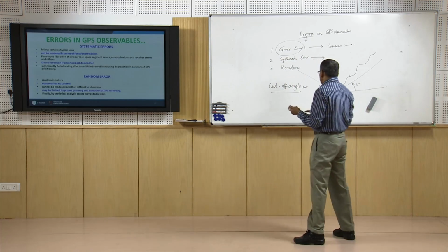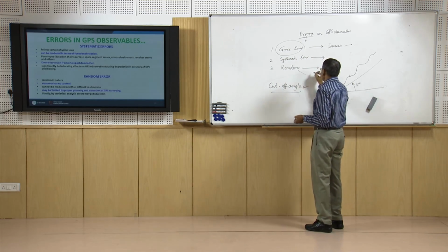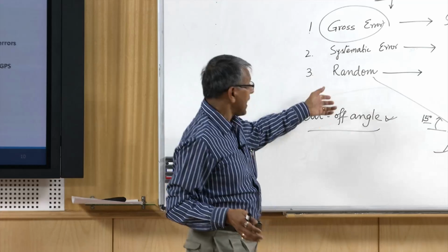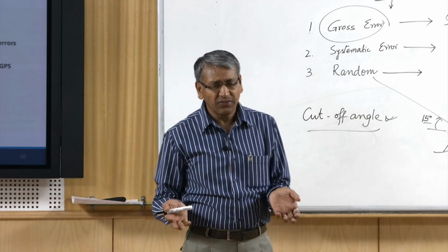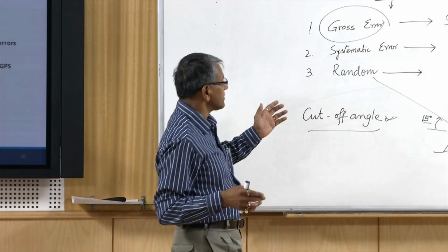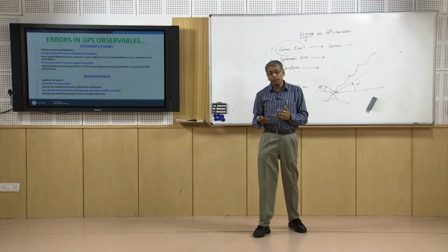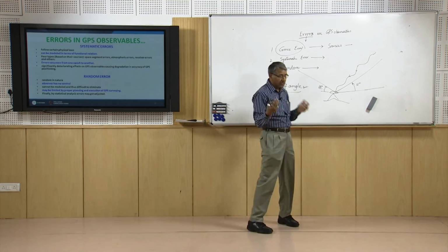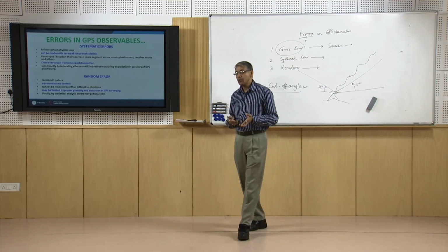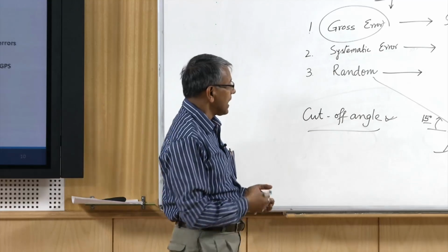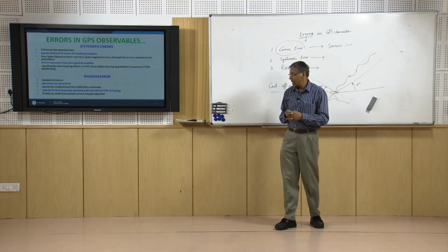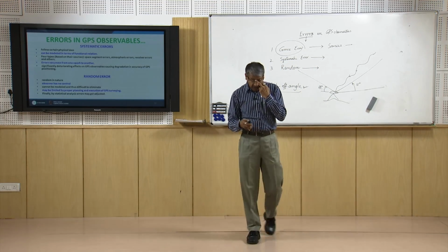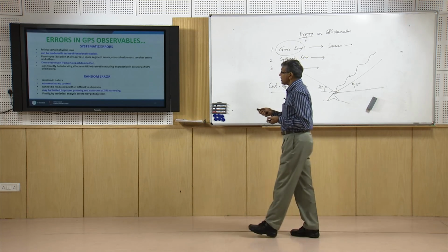That can only be limited by taking proper care during planning and execution of the surveying, and later, after removing the gross error and systematic error when the data are processed, we should check the random error. If it is there, then statistically we have to adjust the error among different parameters so that the effect on position gets minimized. Whatever it is, these errors will be present.